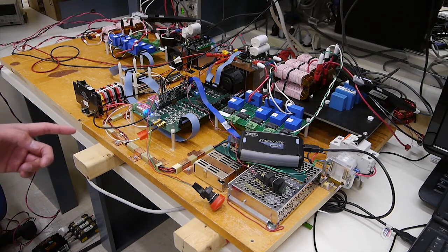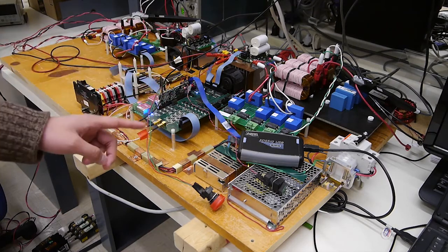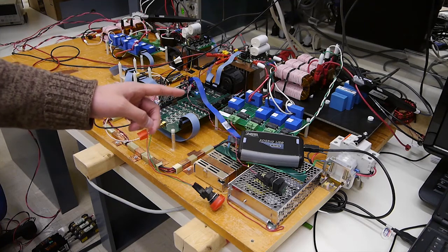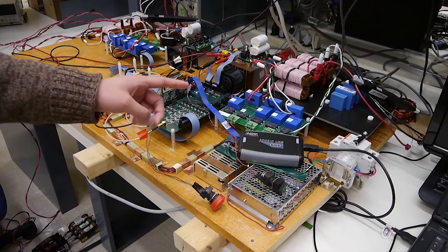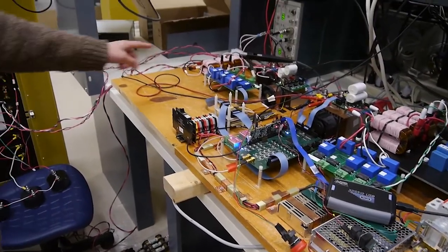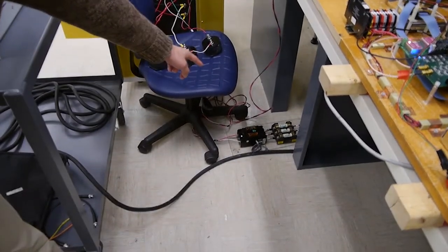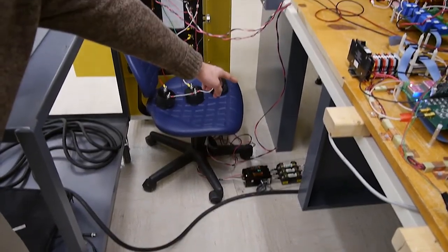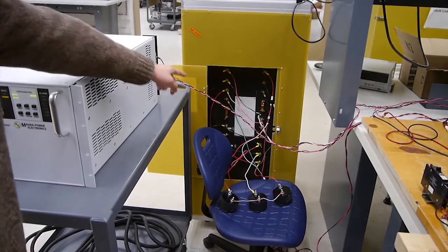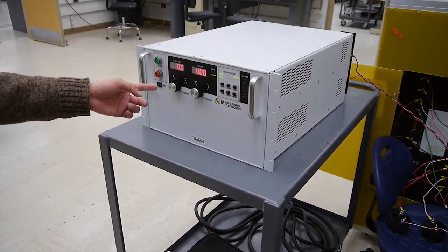Now let's take a look at the testbed for our experiment. This is an inverter which represents our distributed generator. It has a DC source which mimics the PV panel. This converter represents the motor drive front end. And here you can see a switch, which is the PCC switch. Three wires connect to the grid, and that load bank is the local load.